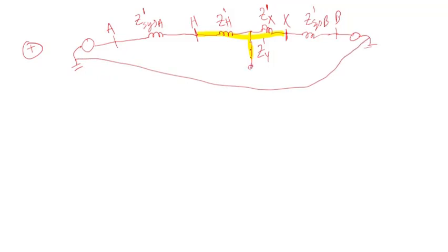But in the positive sequence impedance, this is open. That's why typically in the positive sequence you would not see the T model of the transformer. You would just see the positive sequence impedance of the transformer. But keep in mind, if you have a three-winding transformer, you can get the T model.